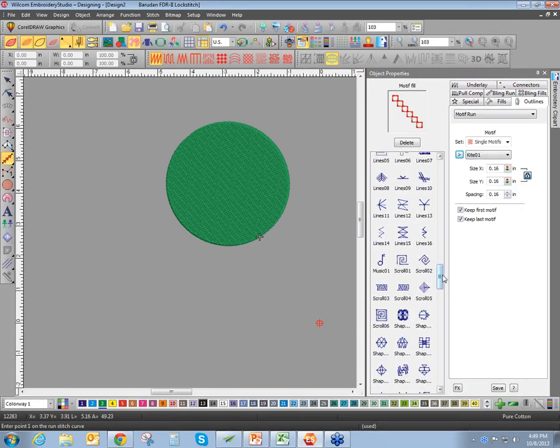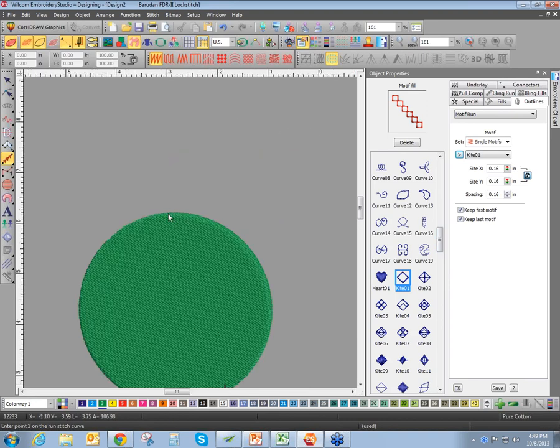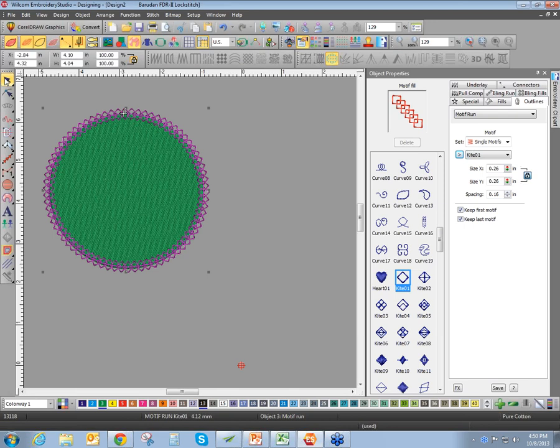So maybe let's do the one that it's on actually right now. I can snap to curve with anything. So talking about digitizing, those previous tools I just used, again, with the right click and left click inputs, it will snap to curve for me on any input I have. If this was a graphic image, JPEG image, it literally would still snap to curve for me. I can actually set how large or small I want that motif to be, and it will take effect. So that's part of the element. That is the motif element.